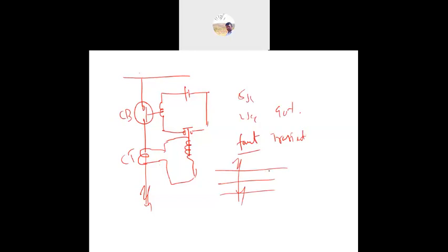Such faults are always associated with an arc. If the line is disconnected from the system for a short time, the arc is extinguished and the fault disappears. Immediately after this time the circuit breaker can be reclosed automatically and the supply restored.